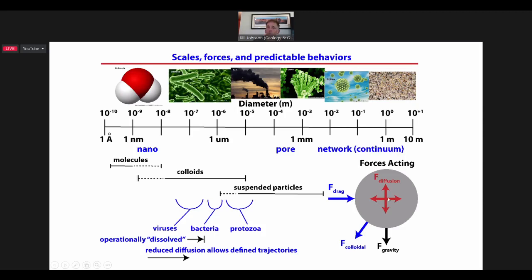So the solutes and the smallest colloids have very high diffusion. They can, in the pore space, diffuse so rapidly that they find surfaces. They can almost be guaranteed to find surfaces. Whereas in contrast, larger colloids have very low diffusion, they aren't guaranteed to find surfaces, and so they will only reach surfaces if they're on fluid streamlines that impinge on surfaces.